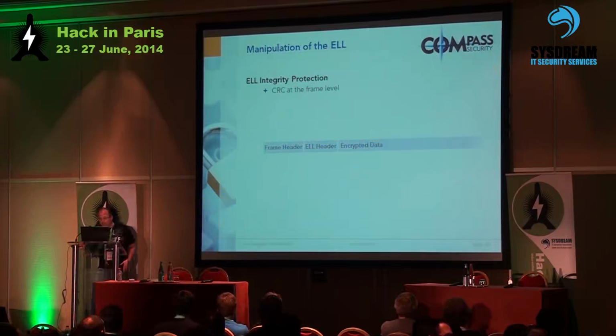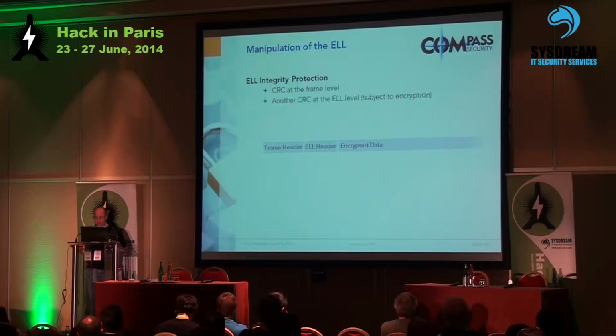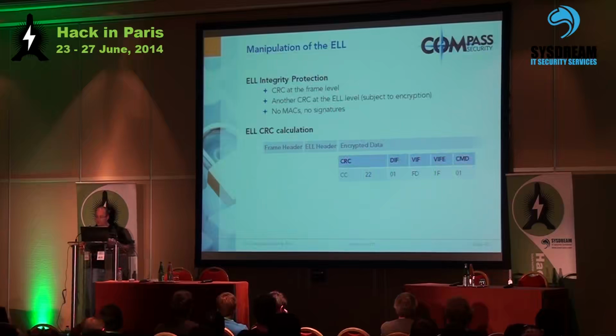Then I had a look at the extended link layer integrity protection. So they were pretty clever. They used CRC, and they did encrypt it actually, in hope no one would be able to manipulate commands. What you see here is a command to switch a meter on or off, the official command. And it basically yields a CRC of CC22.